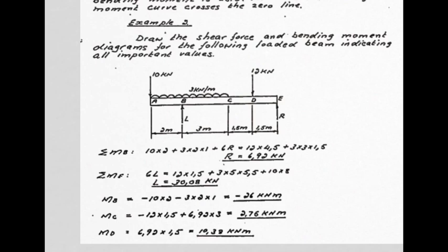Next is the bending moment at B. Put your hand on B, expose the easy side of the beam, which is the left by the looks of it, minus, because it's downward effect, 10 times 2 would be the bending moment caused by the 10 multiplied by the 2, minus the UDL at 3 per meter times 2 meters times 1 meter, distance from midspan to B. So we have minus 26 kilonewton meters as a bending moment at B.